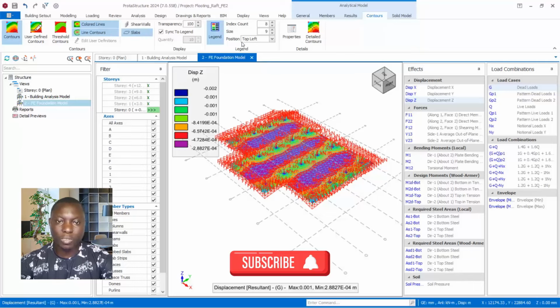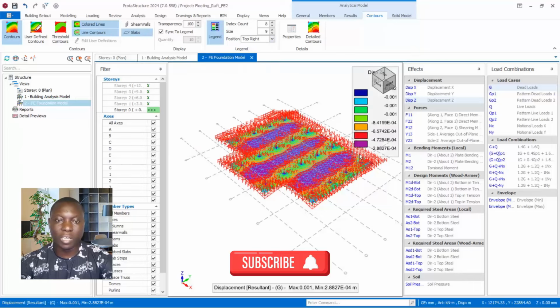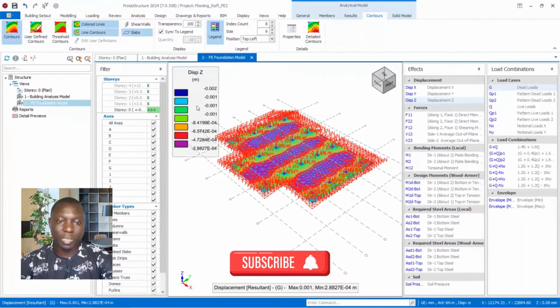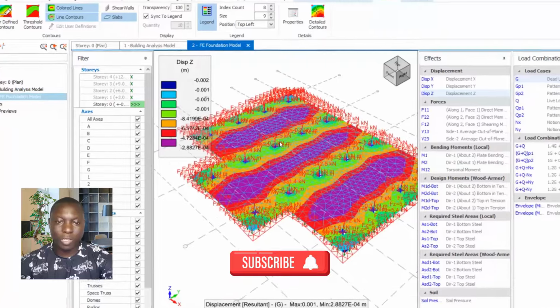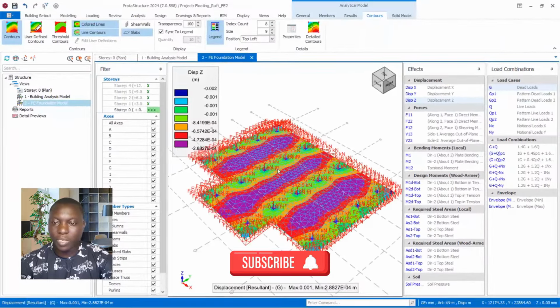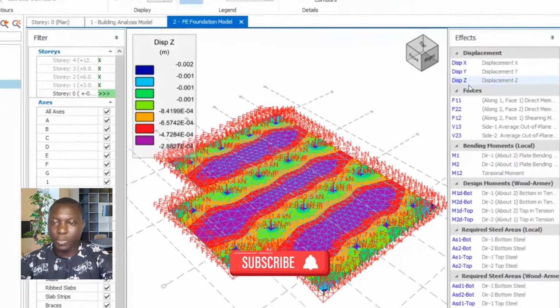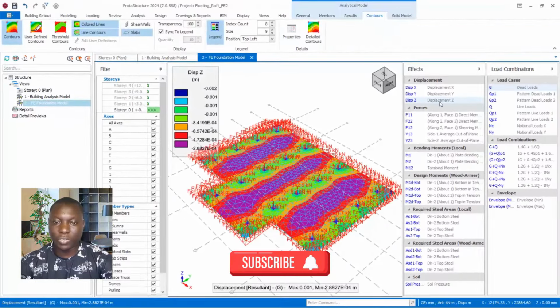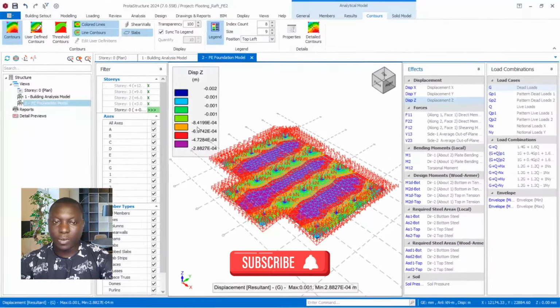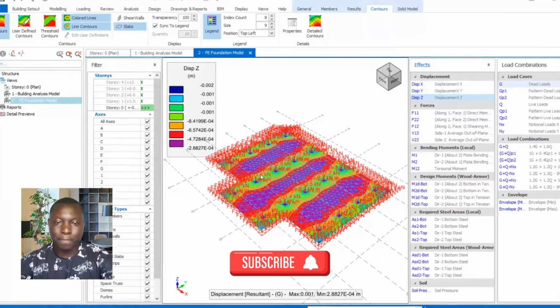You can position the legend very well using these provisions. You see positions, top left; if you click here, top right, it goes to the right. If I use bottom left, it will come here. So you can position it where you can see and read it properly. We really have an issue with this because the program will generate reinforcement based on the result here. Over here we have displacement, in the Z direction, that gave us this contour, and then the figures in the legend right here.